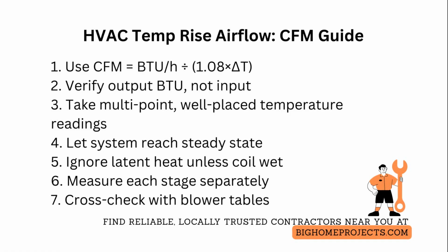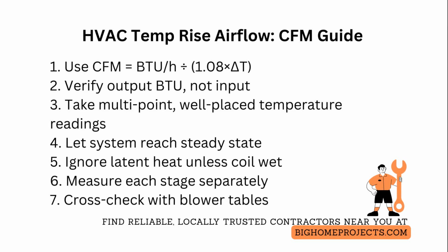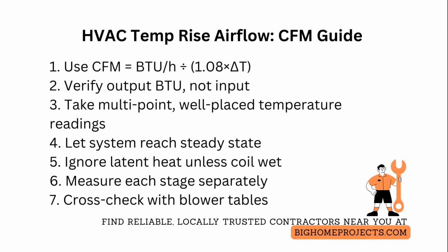Correct for supply air humidity only when the coil is wet in heating with heat pump reheat. Otherwise, ignore latent terms because the formula assumes sensible heat. If you have a two-stage or modulating furnace, measure on each steady state stage and record separate airflow cubic feet per minute, then align blower tables to keep temperature rise inside the manufacturer's window.